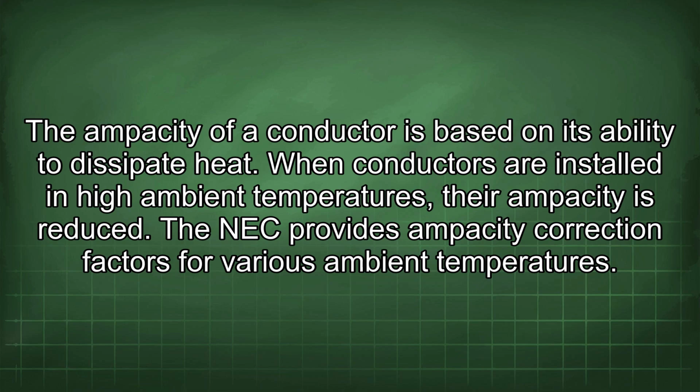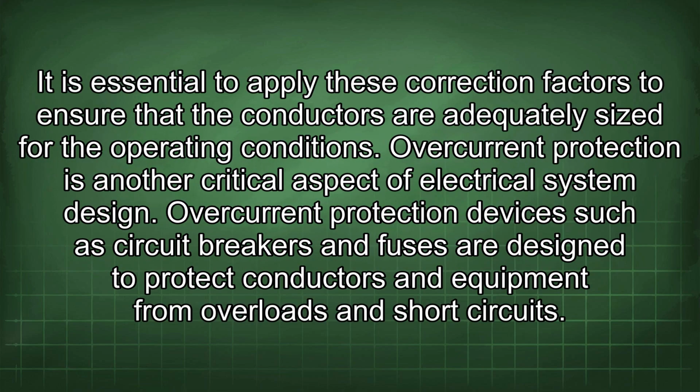The NEC provides ampacity correction factors for various ambient temperatures. It is essential to apply these correction factors to ensure that the conductors are adequately sized for the operating conditions. Overcurrent protection is another critical aspect of electrical system design.